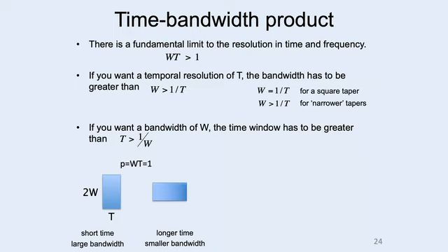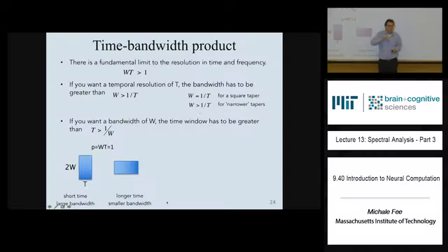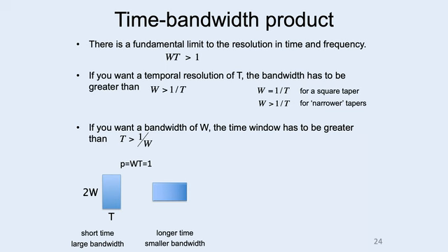So notice that if the time bandwidth product is small, close to 1, the number of tapers you get in this DPSS, this family of functions, is just 1. If p is 1, then k is 2p minus 1, which is 1. So you only get one window. You only get one estimate of the spectrum.